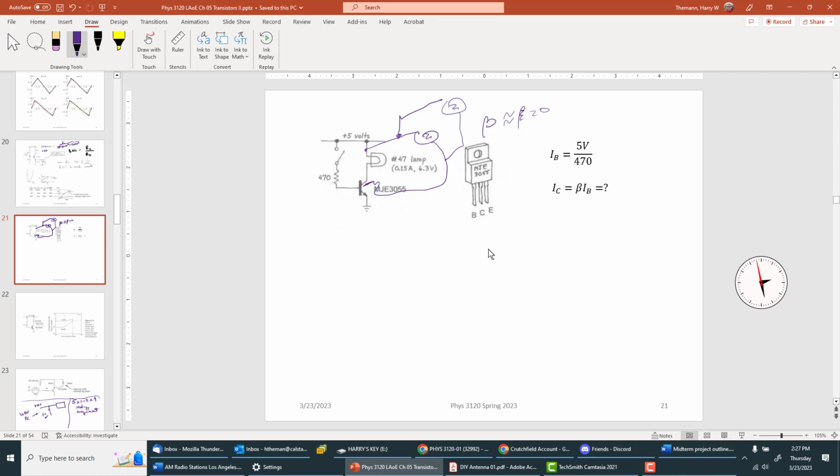to preserve the contacts, number one. Number two, you get to the point where there's so much stored energy that it becomes dangerous. Remember, too, to make an arc, you need 3 times 10 to the 6 volts per meter. 3 million volts per meter. So that's a pretty hefty voltage that all of a sudden is built up, and it's all because of the stored energy. So you're going to hook up those batteries, and when you open the switch, you're going to see a huge spike on your oscilloscope.